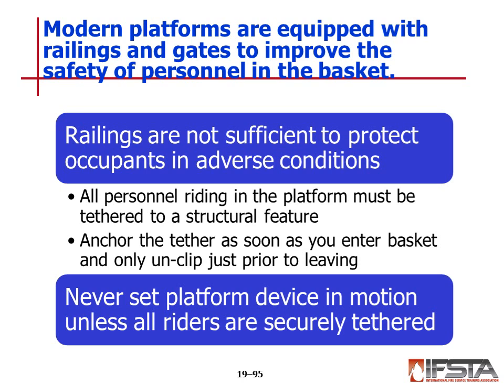Anchor the tether as soon as you enter the basket and only unclip just prior to leaving. Never set the platform device in motion unless all riders are securely tethered to the platform.